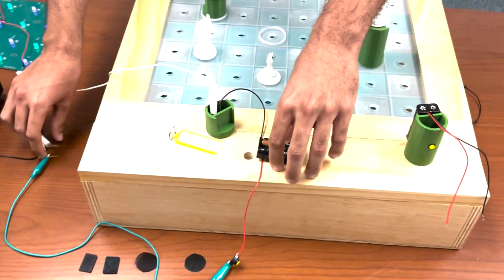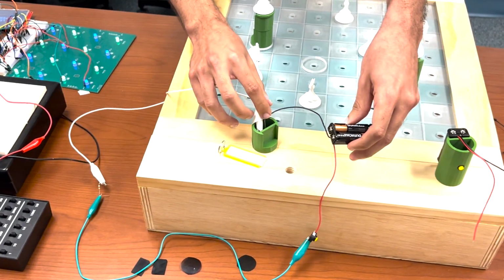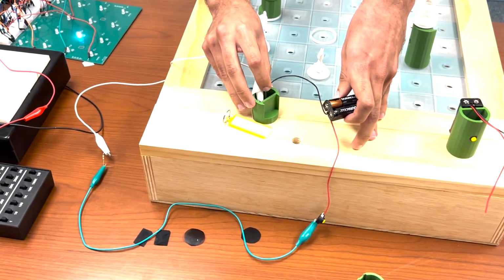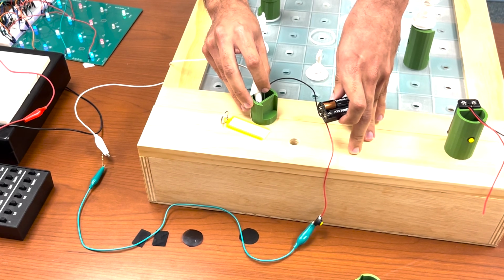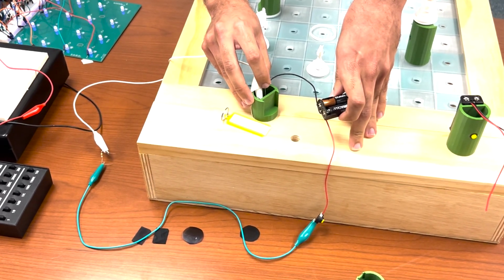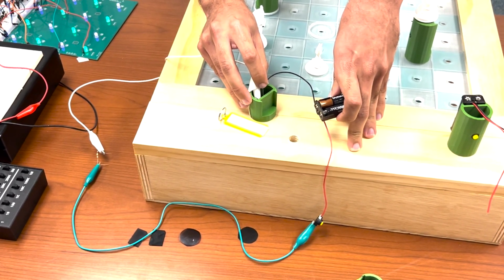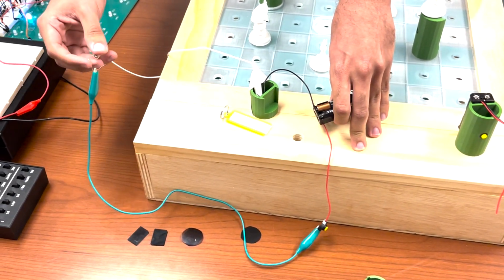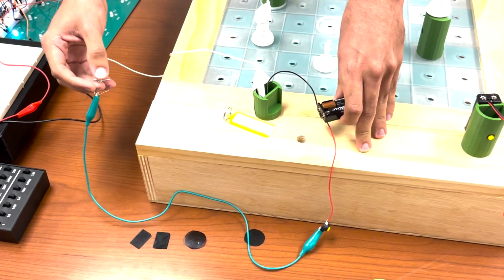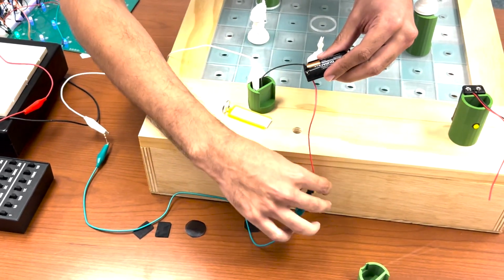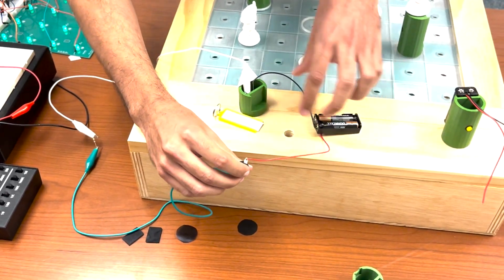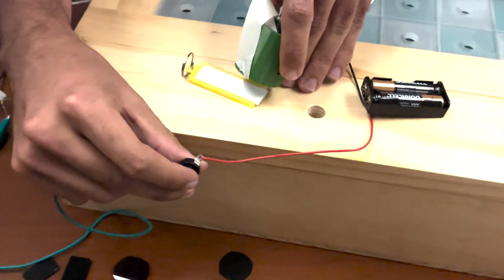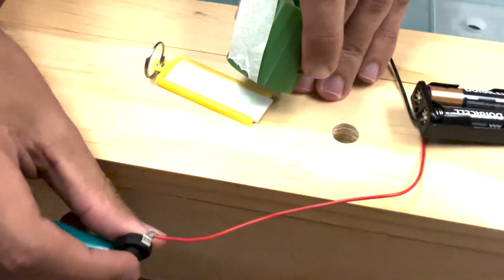And here we would have the circuit, the LED here, which is 940 nanometers, and has a forward current of 47 milliamps and a forward voltage of 1.28 volts, with a resistor around 60 ohms. And here's the battery pack and the switch. We would need an IR card to see the light from the IR LED. Now it's on.